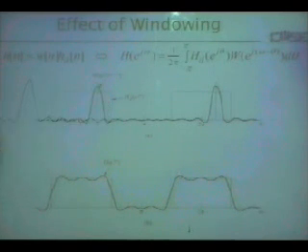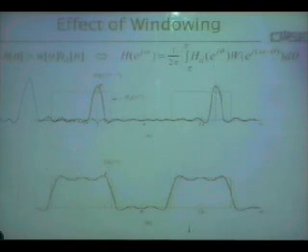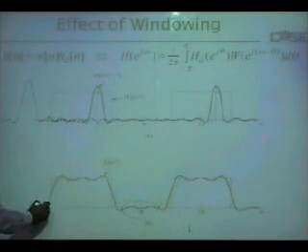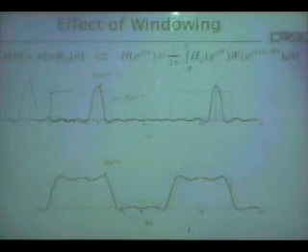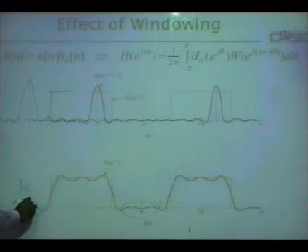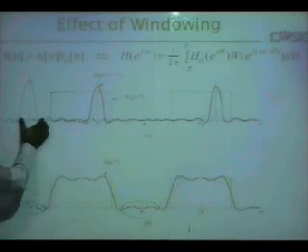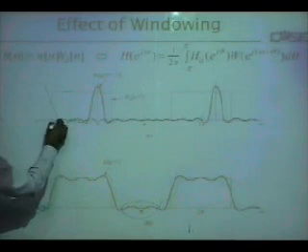The Fourier transform of the window is not in the main rectangle. Okay, so you start seeing something here, which is shown here. So you start seeing something, though you are still away from this line. Okay. So this will cause the stop band ripples. So delta of 2. So it will cause a few delta 2's, there will be some ripples here due to these effects.